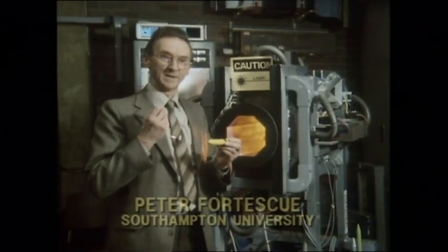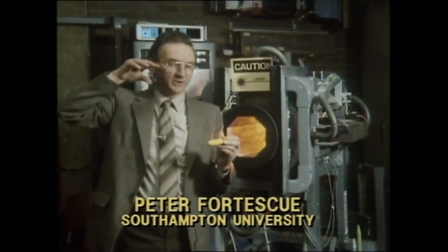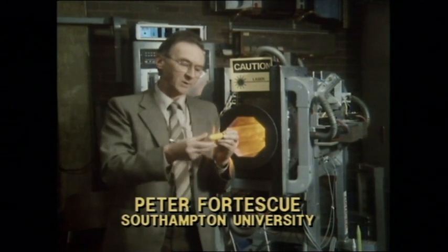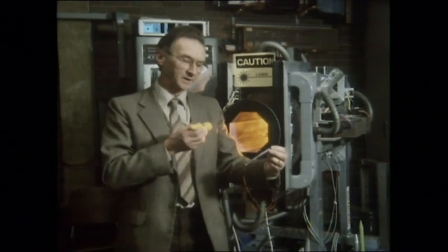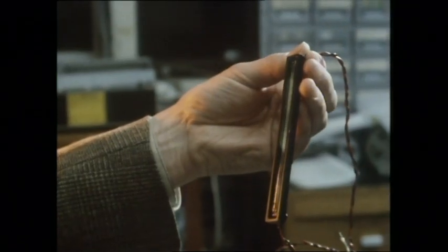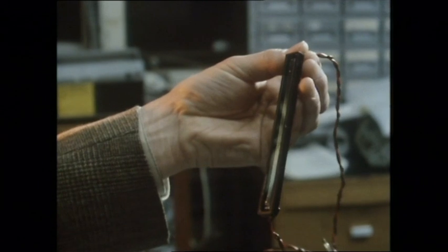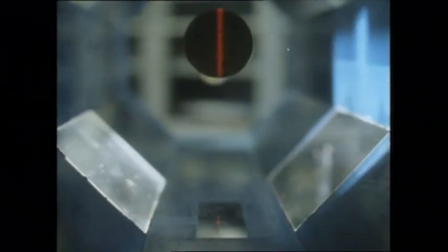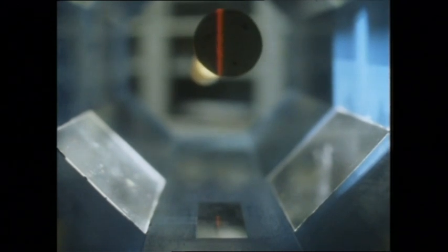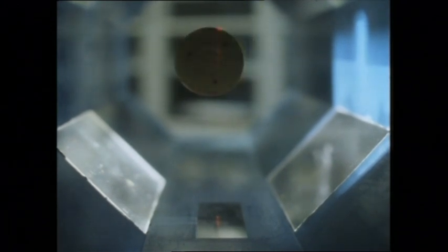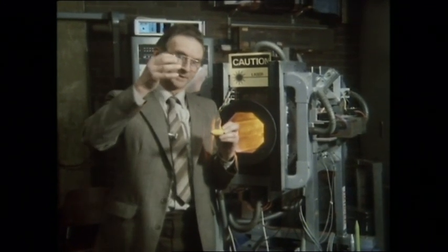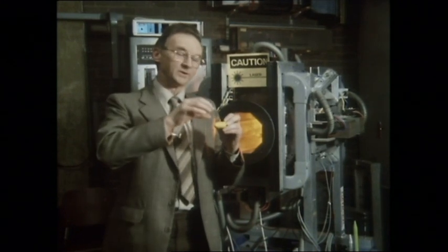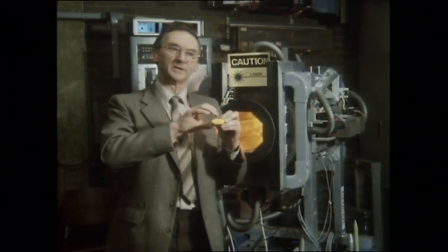If we look at one light beam, the light beam, for example, is shining across the model, and the model will shadow a detector which is on the far side of the wind tunnel. These detectors will give a signal which is proportional to the amount of light falling on them. So as we shadow, a signal from the detector effectively tells us where the model is. That is fed back into the computer, and is fed back to the magnets to control the strength of the field in which that model is sitting.